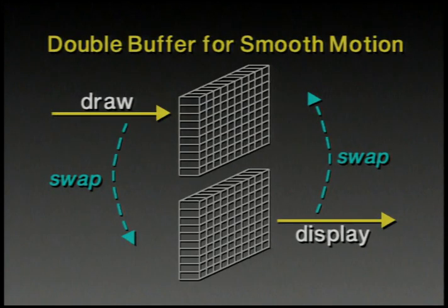While graphics systems designed for two-dimensional rendering typically have only a single frame buffer, three-dimensional systems almost always have two frame buffers. One buffer holds the latest completed image, which is being displayed on the cathode ray tube. The other is used to generate the next image. When the next image is completed, the buffers are switched. This use of two frame buffers is referred to as double buffering.